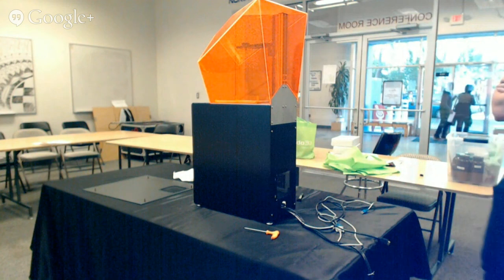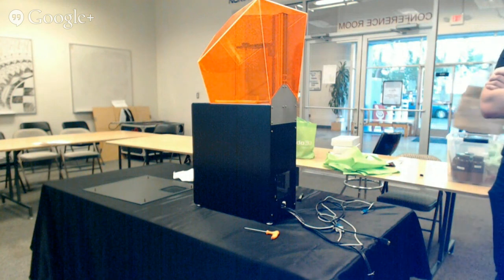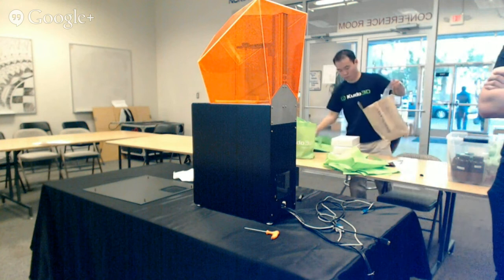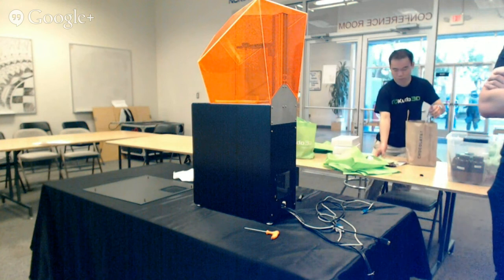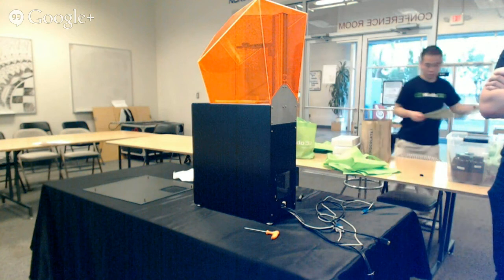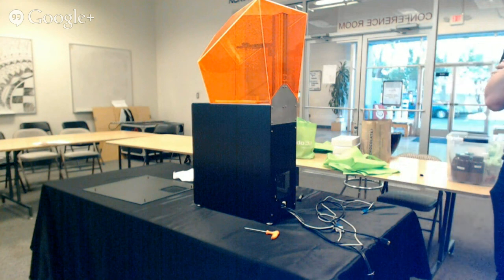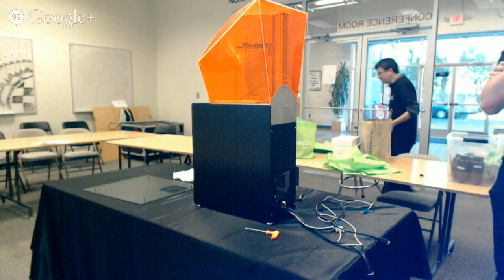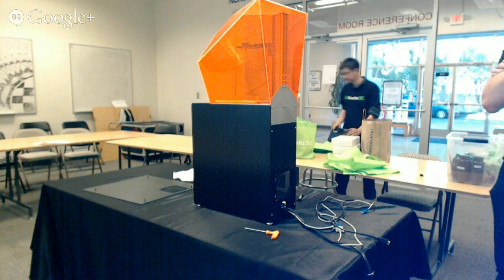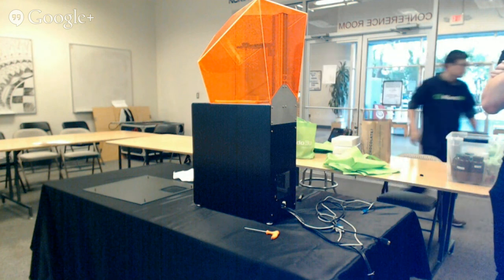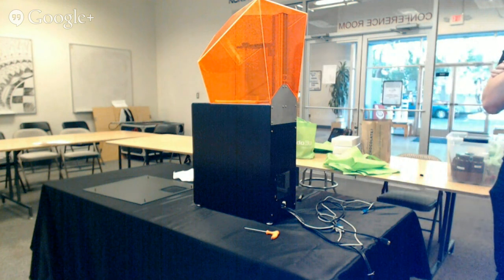Yeah. So every time the plate comes above the surface and then goes back in, it'll push bubbles into it. And usually it's not too big of a deal because if there's enough liquid, you're curing at the bottom. The bubbles are being introduced in the top. Mm-hmm. So the bubbles aren't going to go all the way down unless something really strange is happening.